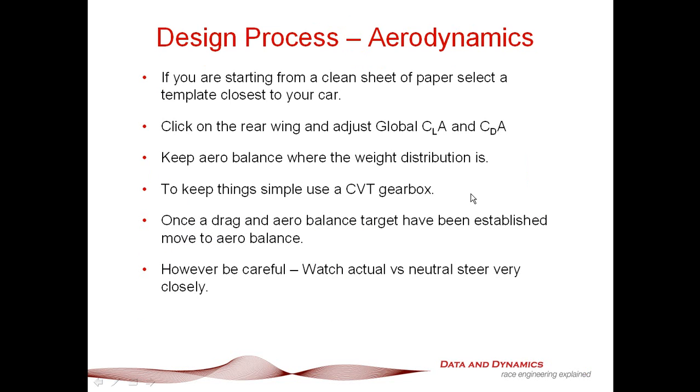However, I want to ram this point home really clearly. Do not get carried away, and watch your actual versus neutral steer like a hawk. ChassisSim is the perfect driver, it does not know fear, so it will tend to shift forward on the aero balance. The last thing you want to do is come up with crazy aero balance figures that, when you put in a driver, are going to scare them. You don't want to do that. I would keep your search ranges to about plus or minus 5%.